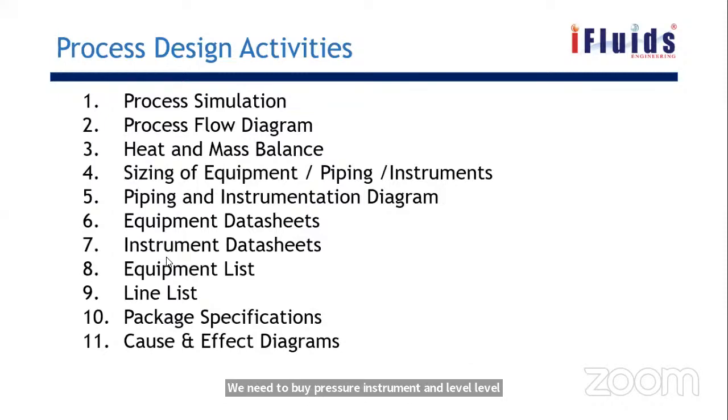Okay. And next is the equipment list. The equipment list is a consolidated list of all the equipment which we talked about in the process flow diagram, with further detail. Let's say for example pump. In the equipment list we'll put that this project is having this many pumps with this many capacities, this many differential head, and this many sizes. In the equipment list, we will fill our process data, and then the equipment list owner will again be the mechanical engineers.